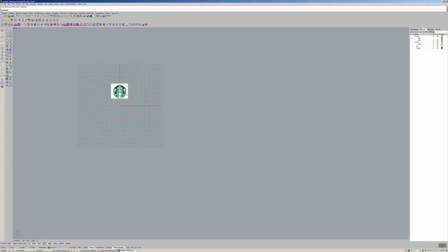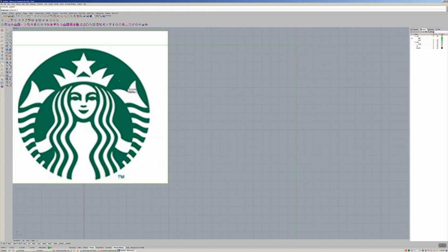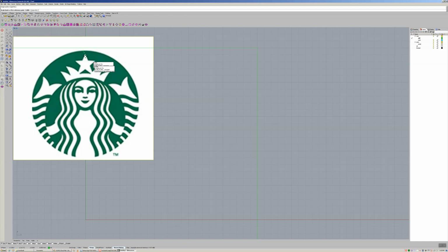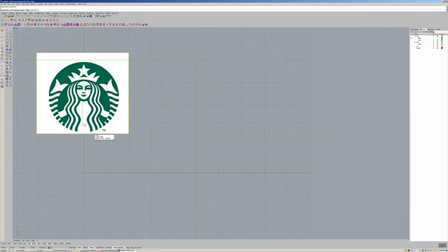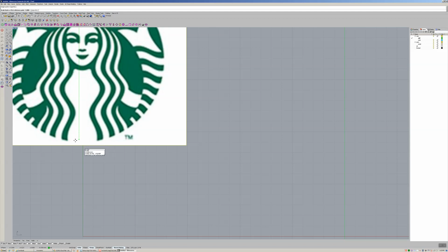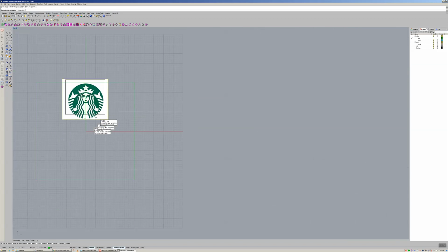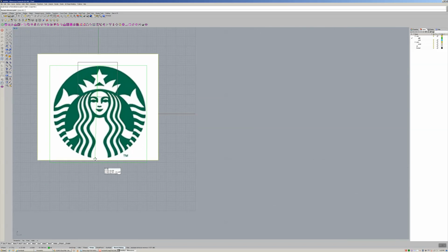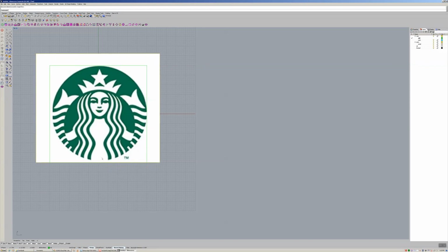Okay. And now the next command we're gonna do is transform scale two-dimensionally. This is going to expand the drawing two-dimensionally. I'm going to left click on it. It's asking me where the starting point for scaling is. I'm going to start at the top of the circle. Then I'm going to hit Shift to give it a straight line, and go to approximately the bottom of the circle. I can't really see it, but you kind of eyeball it. All right, and now I drag down to approximately the bottom where I want it to stop. Okay? Left click. There you go.